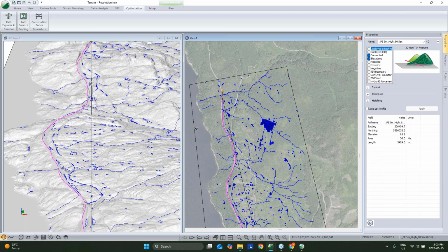So if it's not really driven by the topography and geometry, and you want to check if your alignment is generally following your design speed, a trick you can do there is, if you've got some kind of a line for the existing road, just buffer it out so it has a polygon and reduce the costs for your surfacing on that part of the topo.